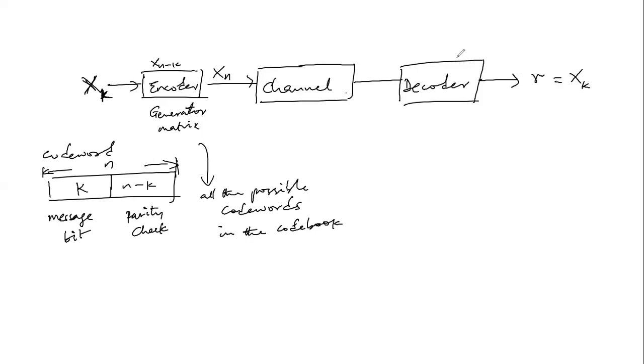In other words, we are going to extract the transmitted message symbol from the encoded symbol, which is the code word, the encoder output S_n. So there must be a system to recover what was transmitted based on the generator matrix, and that is the parity check matrix, which is used for syndrome decoding.